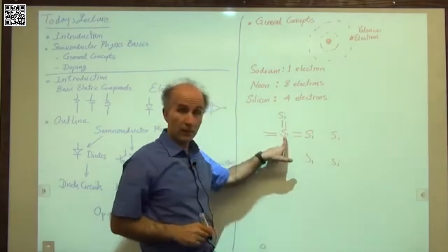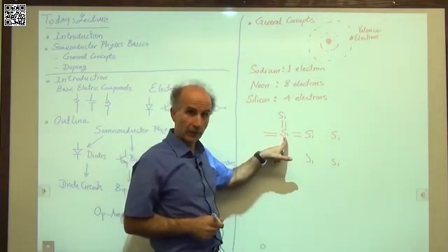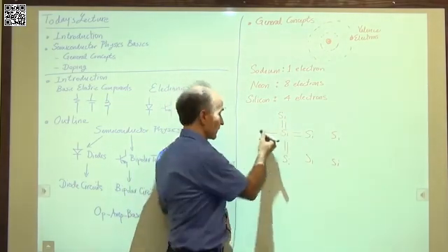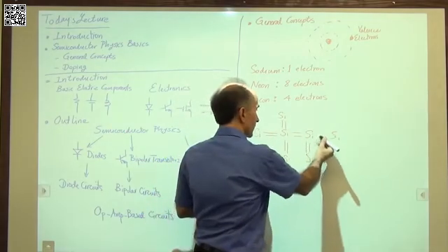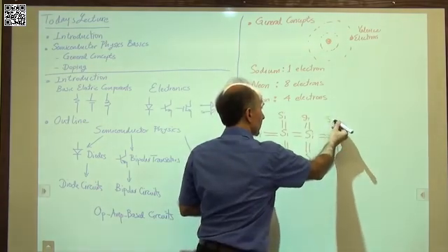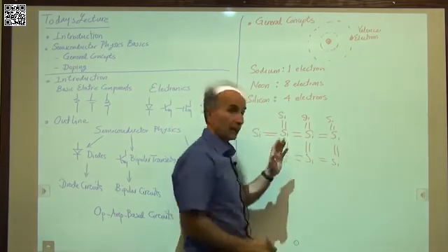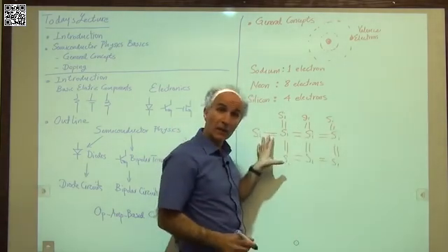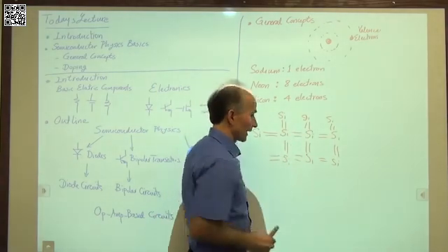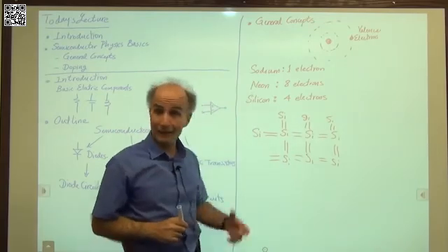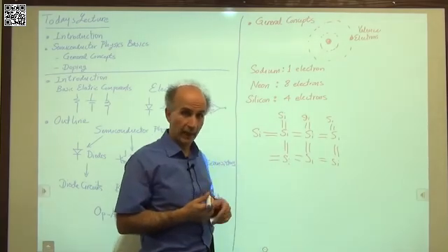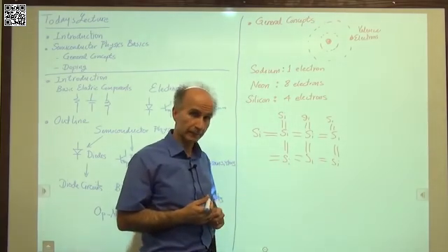So now this silicon, some of the time, has 8 electrons, so it's complete, because it has 4 of its own, and then it's borrowing 4 from these 4 neighboring atoms. And so on. This continues everywhere. These bonds are formed everywhere. So you can see that this is a very regular and clean array of atoms, very organized, and that's what we call a crystal, or a lattice. So silicon has the ability to do this. With proper processing of silicon, we can create a silicon crystal. And that's what we use in semiconductor physics.